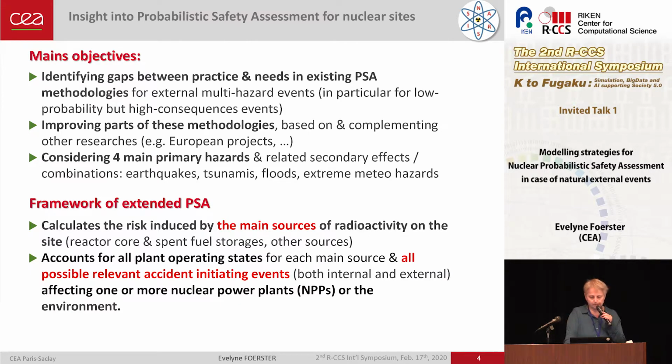PSA is the name for probabilistic safety assessment, where we try to calculate the risk induced by main sources of radioactivity related to the plant, and also to account for all possible plant operating states and for each source of possible risk, and also trying to simulate relevant accident initiating events, which can be internal or external or combined, and which can affect the site or many sites. So this is the usual way of doing.